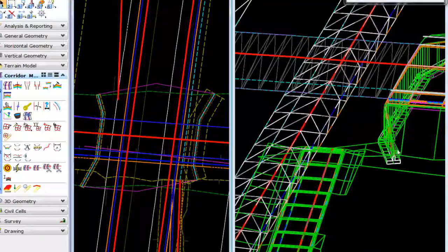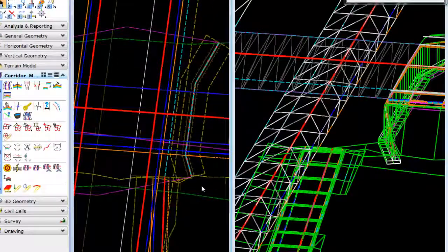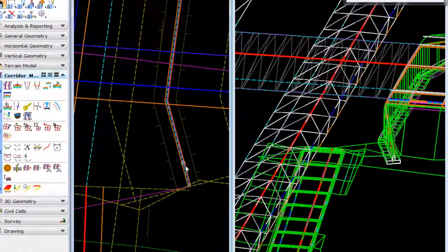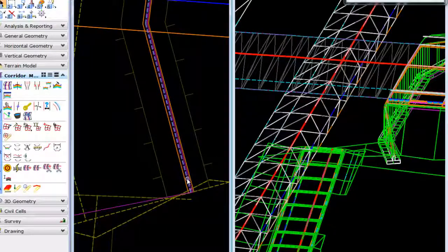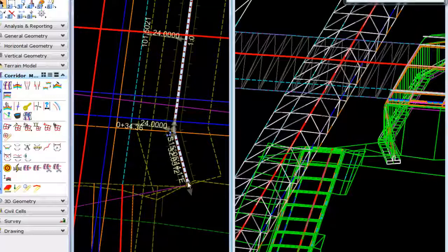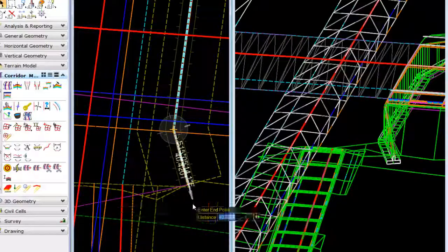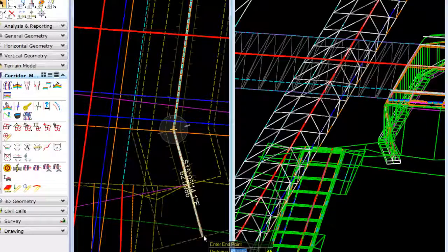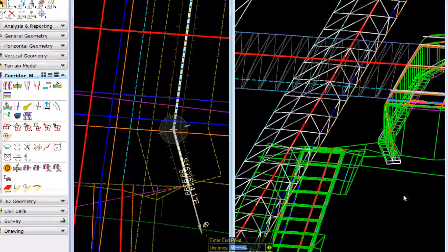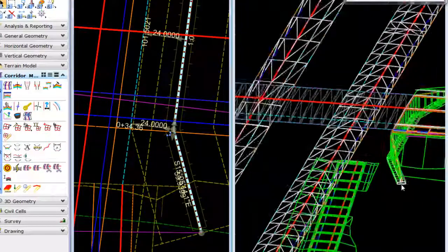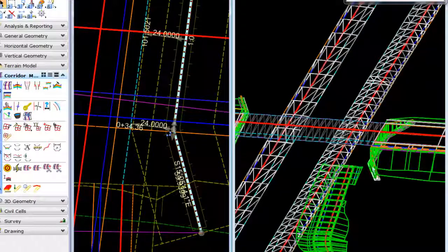However, down here in this corner I see we didn't extend our abutment wall out quite far enough, so I want to grab that dash line, grab that move point and simply extend that out, and there we go. So now I have my trim.